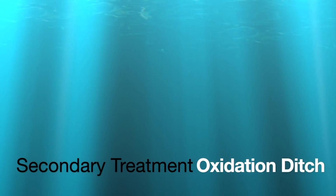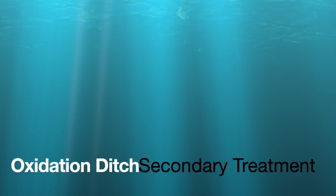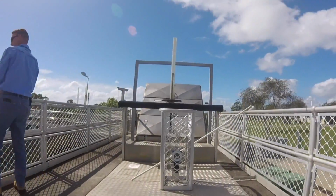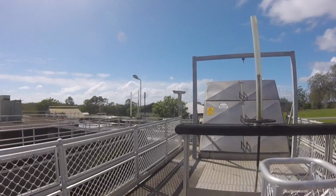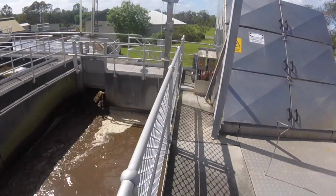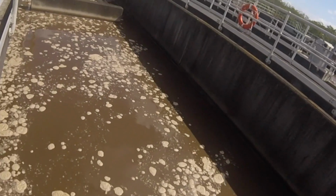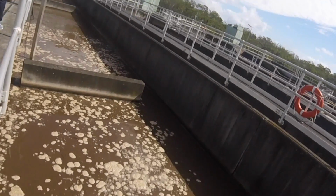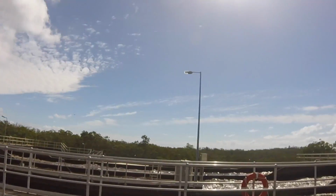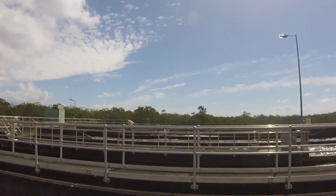In the secondary treatment phase, a BNR oxidation ditch is used. A BNR oxidation ditch is a modified design aimed at nutrient removal using biological means. This is achieved by having an anaerobic chamber before the ditch for phosphorus removal, and the ditch itself is divided into anoxic and aerobic zones for nitrogen removal. The mixed liquor or return activated sludge (RAS) is recirculated from the aerobic zone to the anaerobic zone to maximize phosphorus removal.